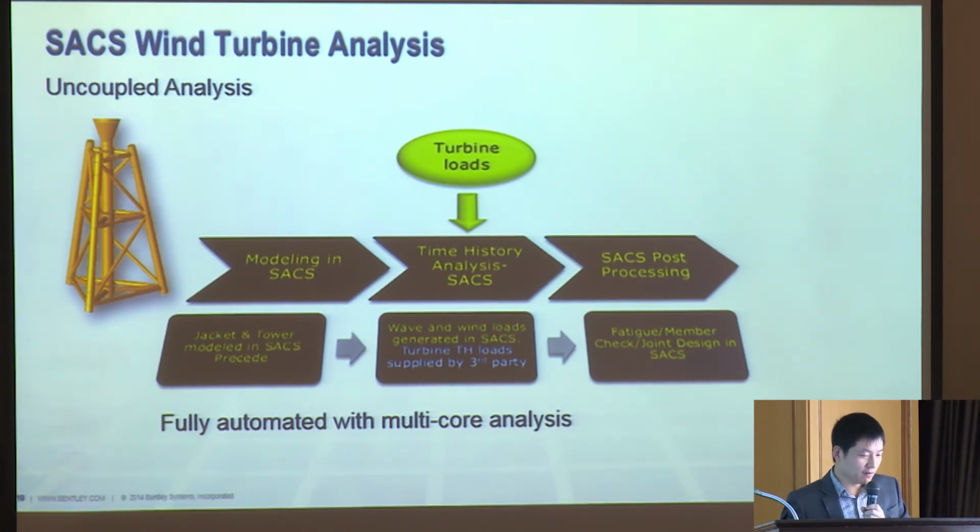First, the foundation structure, the jacket and tower, are modeled in SACS Precede. And the turbine loads are input in SACS as time history loads. Of course, the turbine time history loads are supplied by third parties like Bladed or FAST.